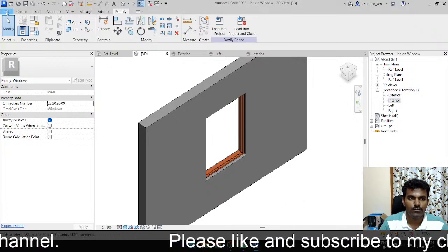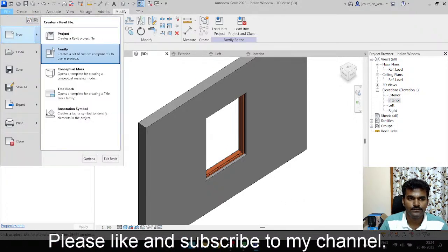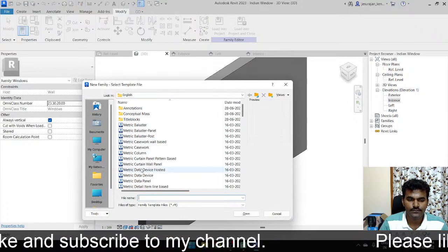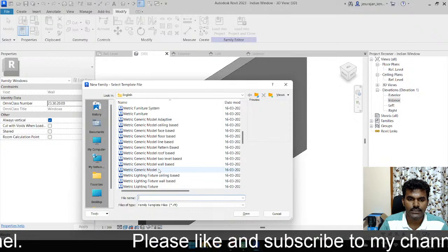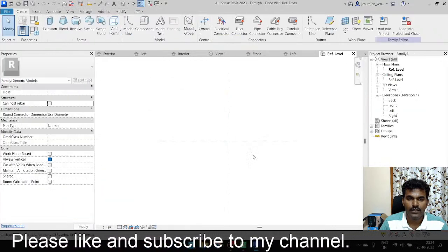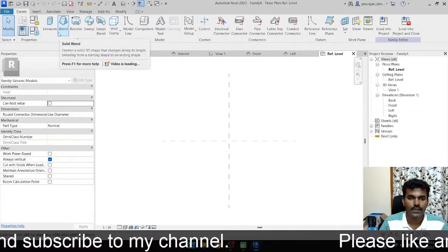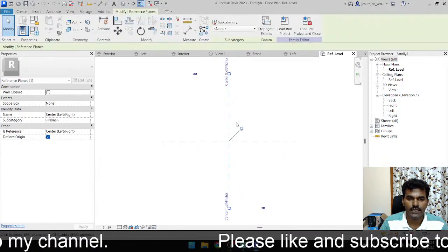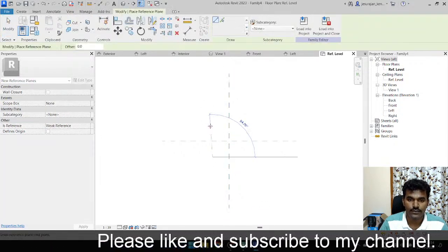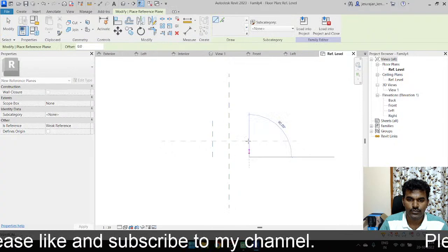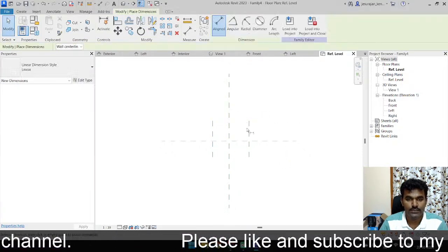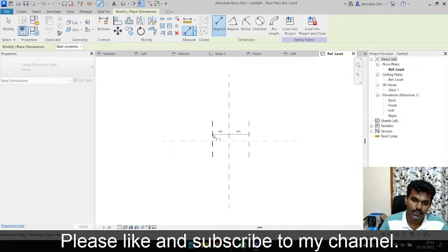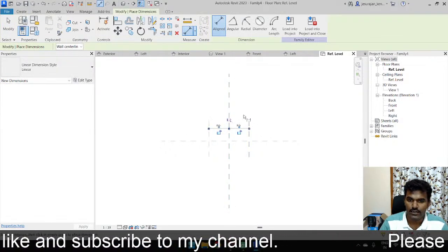I'm going to go to File, New, select Family, metric generic model, open here, and what do I need? The length of the rod and the diameter of the rod. Just draw two reference planes for the length. Just keep it as center and locked.